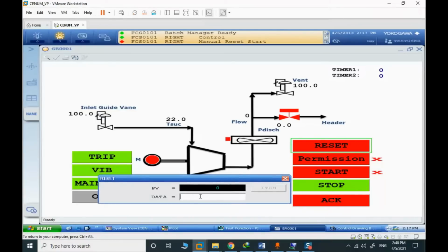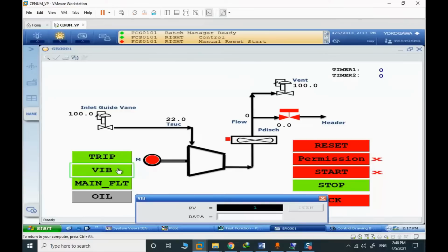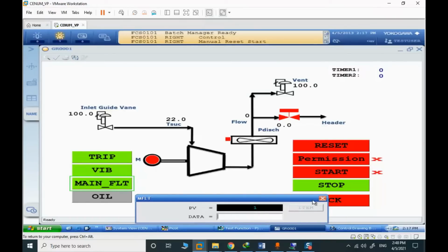When we are in the out of service mode, the temperature values are ambient temperatures, and pressure and flow are 0, valves are all open, and we consider that vibration, manifold, and other trip signals are normal. They are normally true. Vibration is zero, is true. It's normally NC, normal closed.